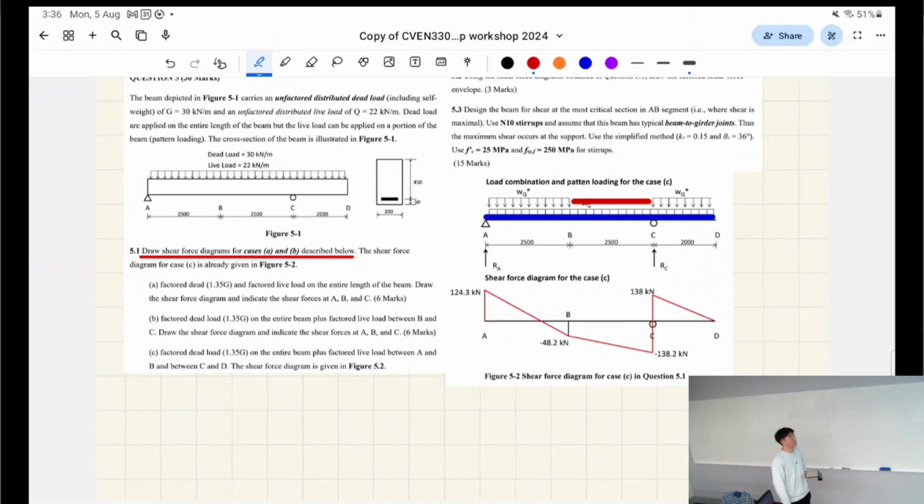Live loads are things which move around, like humans, like traffic, in the case of bridges, for example. It's things that can vary. So we're varying where the live load could be positioned, okay? When you have live load acting on an entire beam, generally it causes more loading on the support, okay?